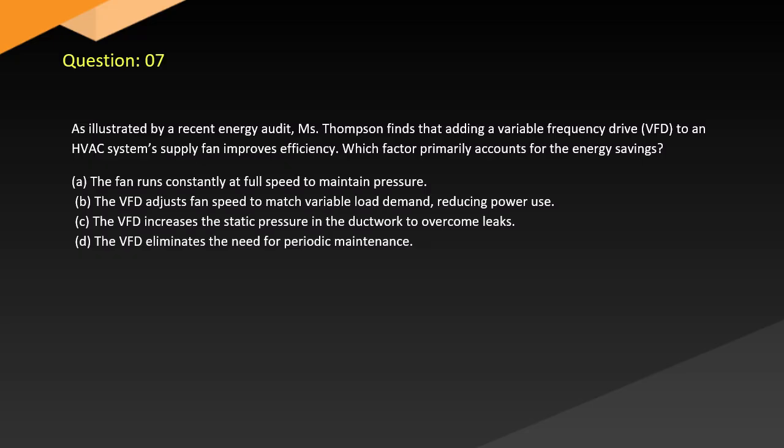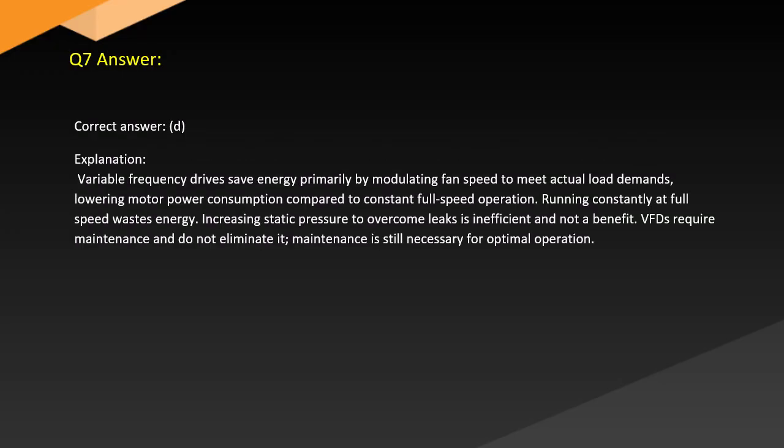C. The VFD increases the static pressure in the ductwork to overcome leaks. D. The VFD eliminates the need for periodic maintenance. Answer. Correct answer. D. Explanation. Variable frequency drives save energy primarily by modulating fan speed to meet actual load demands, lowering motor power consumption compared to constant full-speed operation. Running constantly at full speed wastes energy.